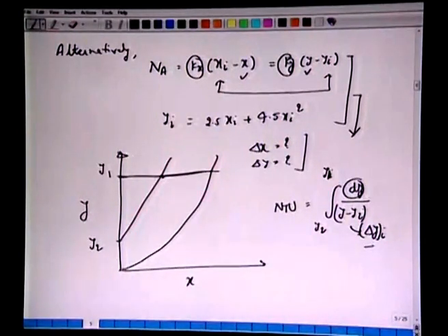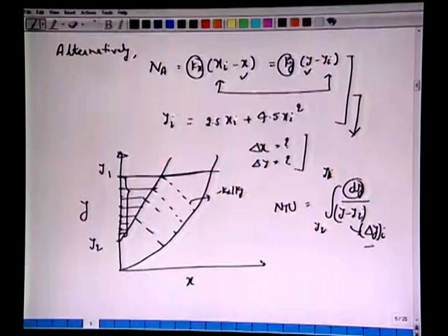You will divide this y1 to y2 in several dy, all right. So, you will take several of such sections, maybe 10, and obtain this. So, you have y1, y2, y3, y4 between these two domains, and from each line you will draw this parallel line with slope minus kx over ky to obtain yi corresponding to this y1, another yi corresponding to this. So, we have all yi's, and then we can do this calculation for number of transfer units.